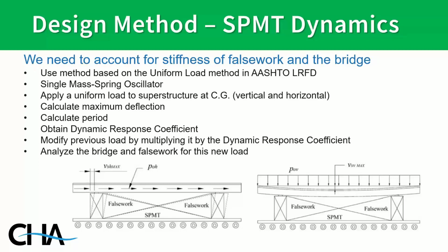both horizontal and vertical had a significant plateau at the lower end of the period. So for the preliminary design by the designer, we developed an equation that you can calculate the response of the bridge when you don't know the exact false work that's going to be used. You can conservatively design for that plateau. So we came up with a simple equation to calculate the horizontal dynamics and the vertical dynamics without even knowing the stiffness of the false work. And that is included in the guideline as well.